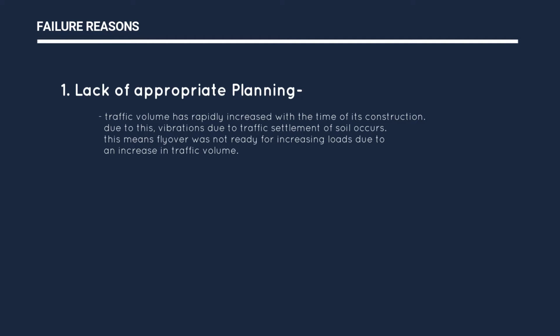Lack of appropriate planning. Traffic volume has rapidly increased since the time of its construction. Due to this, vibrations from traffic cause settlement of soil. This means the flyover was not ready for increasing loads due to an increase in traffic volume.